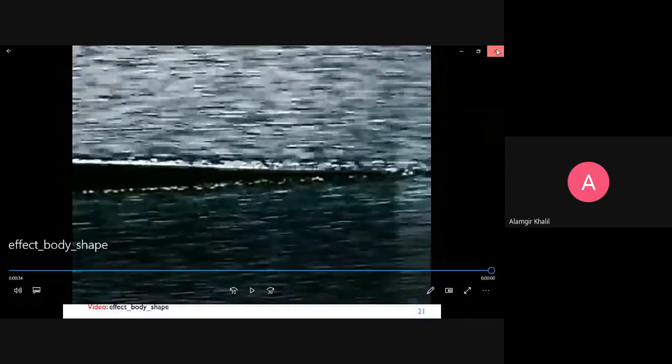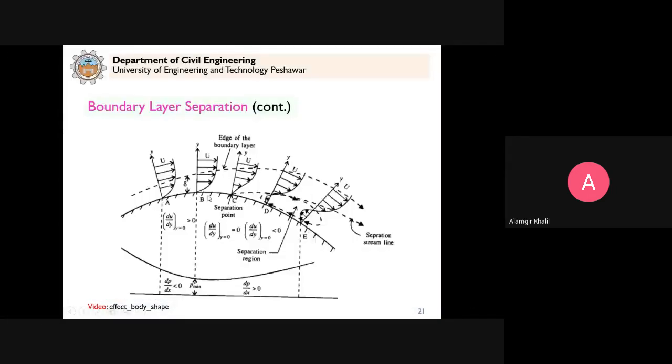But you can see that if we have a flat plate, then the flow separation is avoided. So now you know that when we have a curved surface, we can observe this flow separation or boundary layer separation, clear? For a flat plate, the boundary layer will stick to the entire surface till the end. Now, why does this phenomenon occur?